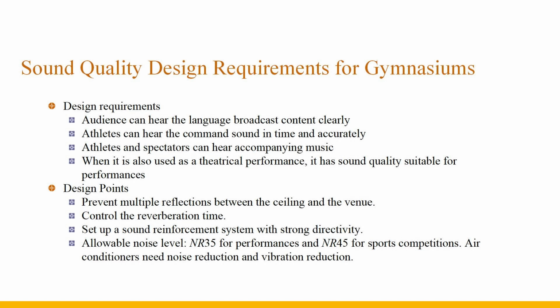Gymnasiums include track and field gyms, ball gymnasiums, swimming pools, and comprehensive gyms. The sound field conditions are quite different from the auditorium mentioned above. The main factors are: first, large volume, large audience, and high noise. The venue is large and open, the ceiling is high, the seats are hard, and the sound absorption is small. Second, the roof span is large and concave surfaces are often used, which easily generate multiple echoes. Third, a variety of functions often double as a sports venue, performance venue, etc.